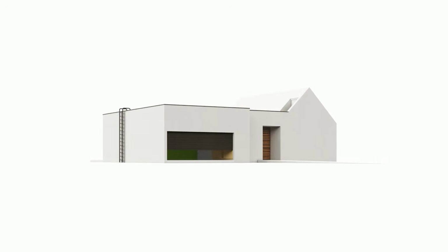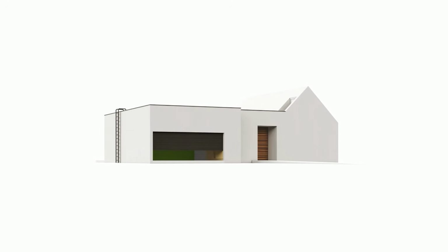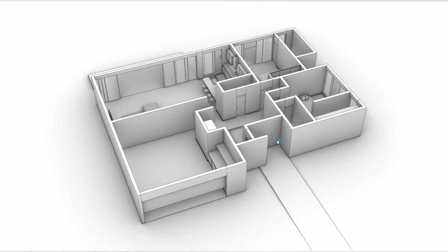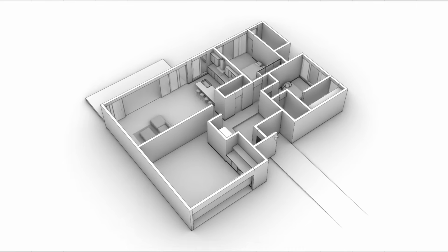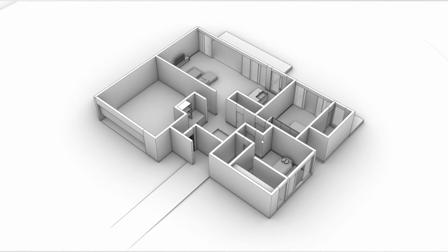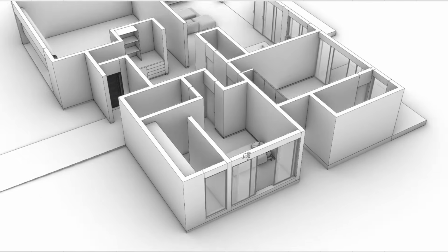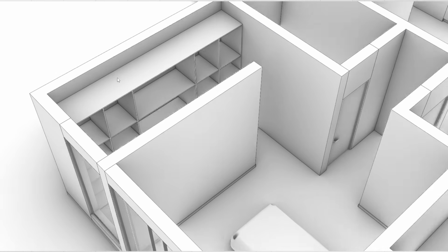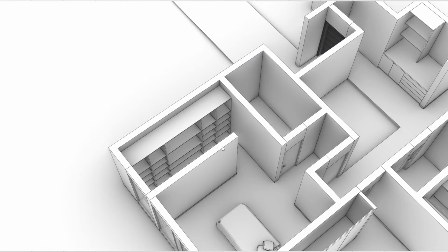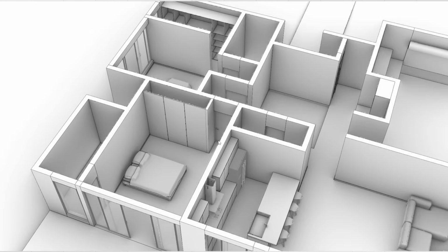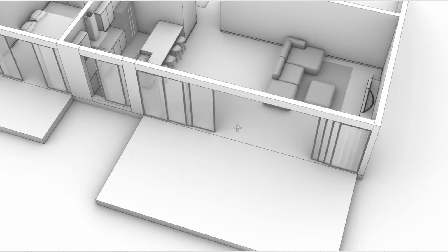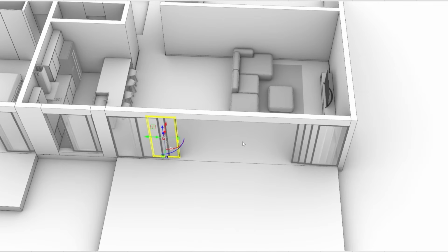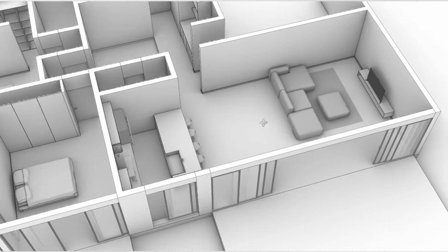And well, in this video, we went step by step through the complete modeling of a modern villa in Rhino. From importing the AutoCAD plan and creating the walls and floor, to modeling the pitched roof, terrain, windows, doors, interior spaces, kitchen cabinets, and even details like baseboards, parapets, and roof flashing. The main goal of this video was to understand the overall architectural modeling workflow and to see how a complete project can be built step by step inside Rhino.